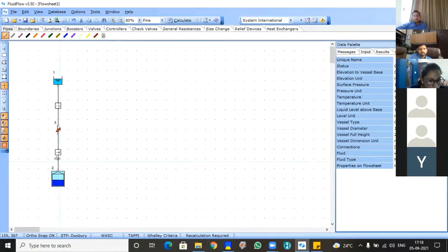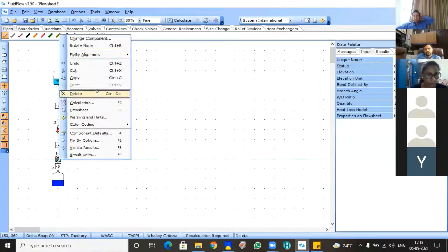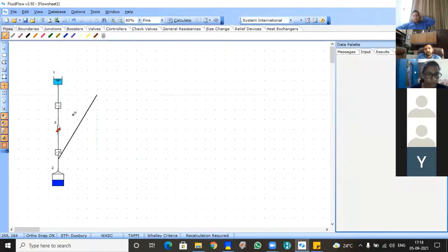Ma'am, this PSV is on the top of some vessel, right? So this gas is going to go from where? From the vessel to the PSV, right? And from PSV to this tank represents the PSV outlet condition, and this vessel represents the PSV inlet flange condition, right? So we cannot just have PSV as standalone. That's why we have to provide this vessel and this tank.